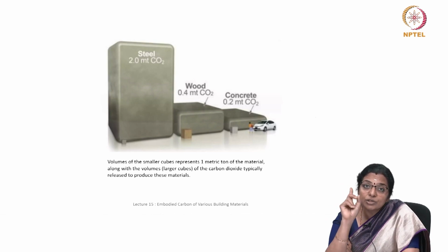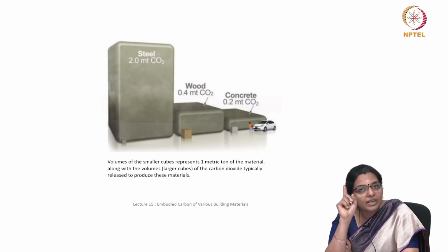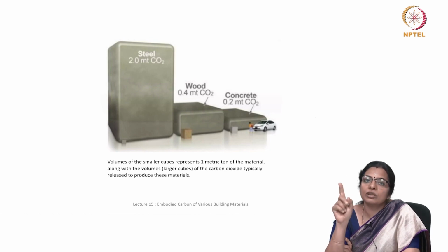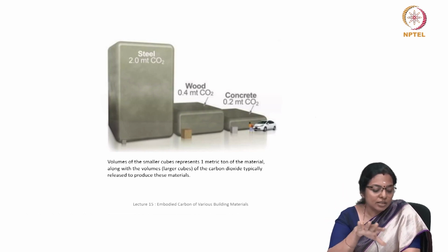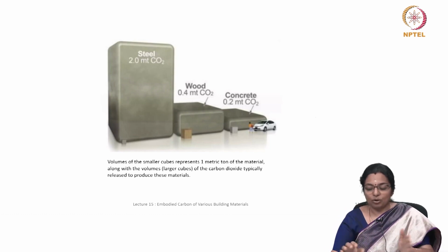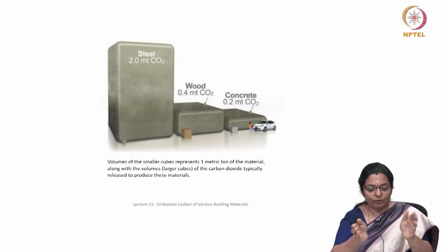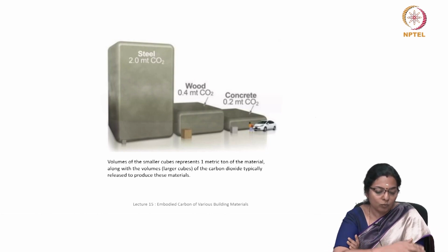But when it comes to reinforced cement concrete, its embodied emission is very high because you need to factor in the use of steel. So this is the graphical representation to have a perspective of which building material gives more emissions.